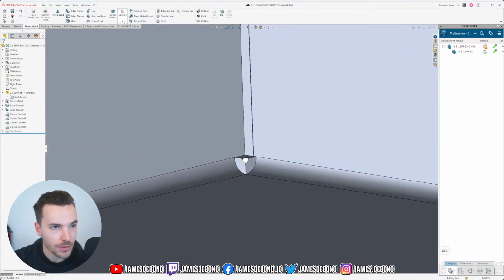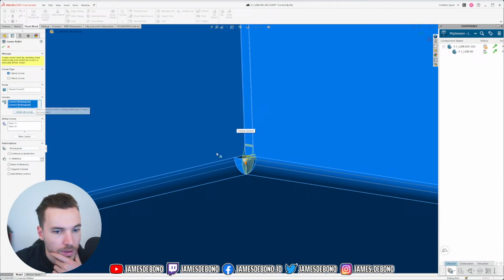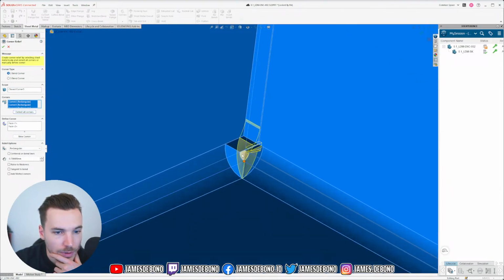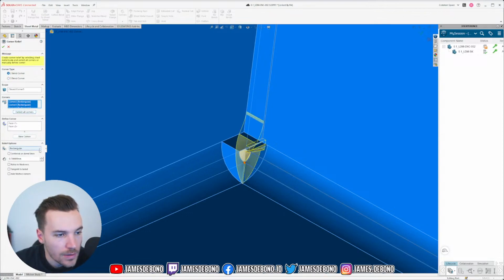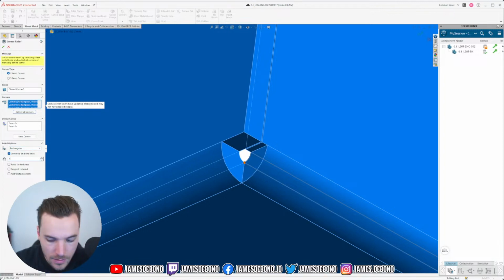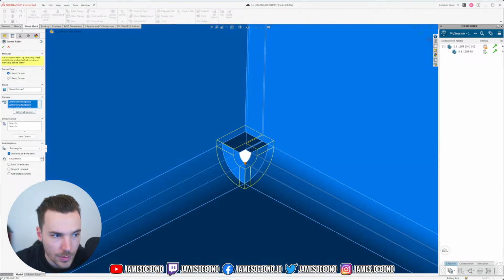So there's also another SolidWorks feature for this called corner relief. And I can collect all of the corners. And I can try some different corner styles here. This is a 2-bend corner, I think. Yeah. So then I can center the corner on the bend line, and the rectangular corner is essentially what I already have, so I can just make it bigger.